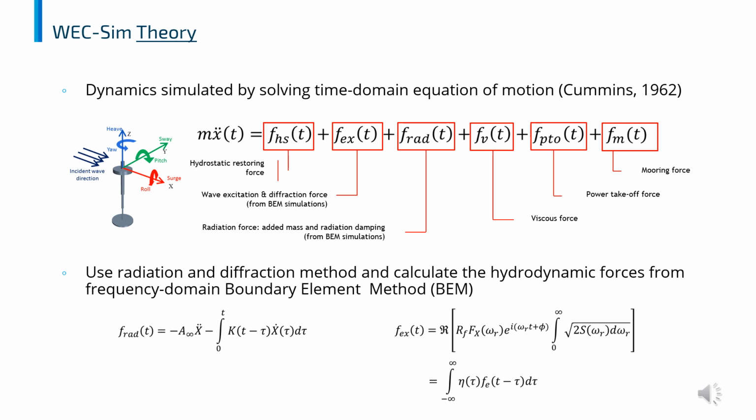summation of our hydrostatic restoring force, our wave excitation and diffraction, which is from coefficients from boundary element method solutions, our radiation force, which incorporates added mass and radiation damping, also from our boundary element method solutions, a viscous force, which can incorporate nonlinearities, and PTO and mooring forces, which are also externally defined and can incorporate nonlinearities.